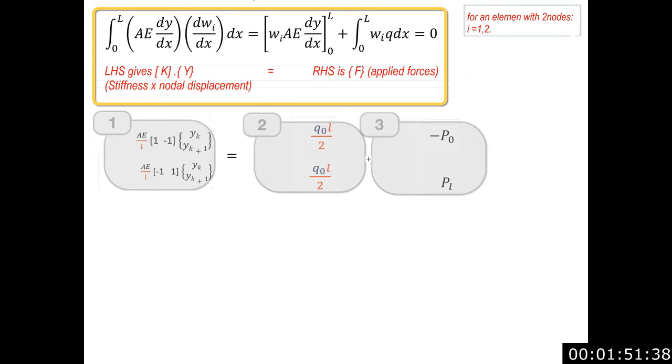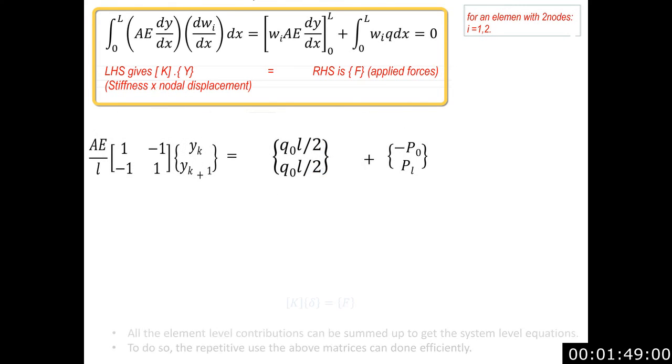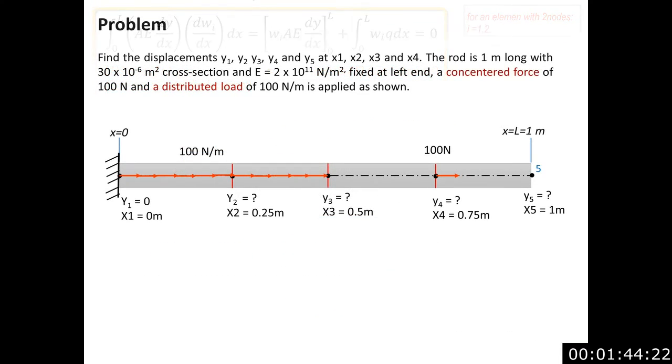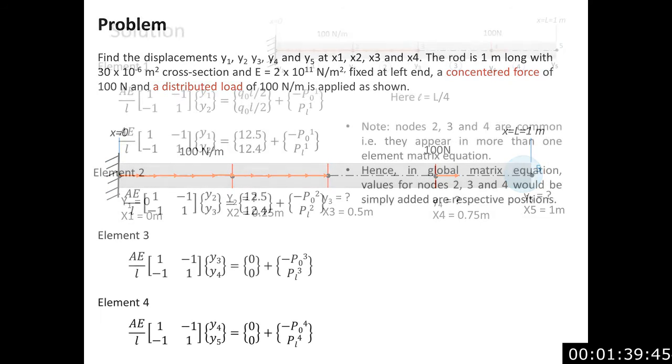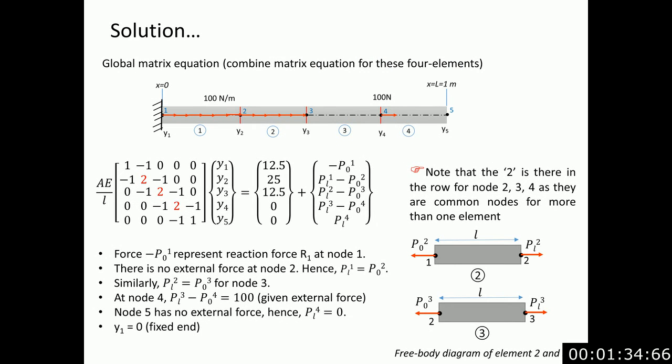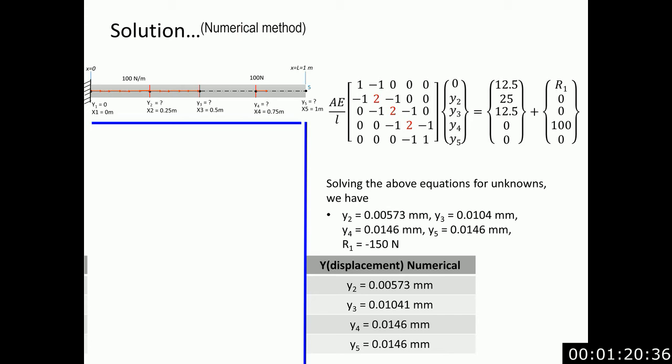We will use these equations to solve our defined problem. Since in our problem we have taken 4 linear, well-connected elements and 5 nodes, we will have 5 nodal equations which are combined in such a way that the connectivity is maintained. We will get a global set of equations. Using a computer program to numerically solve this set of equations, we get the nodal solution. These nodal solutions are interpolated over the length of the element.